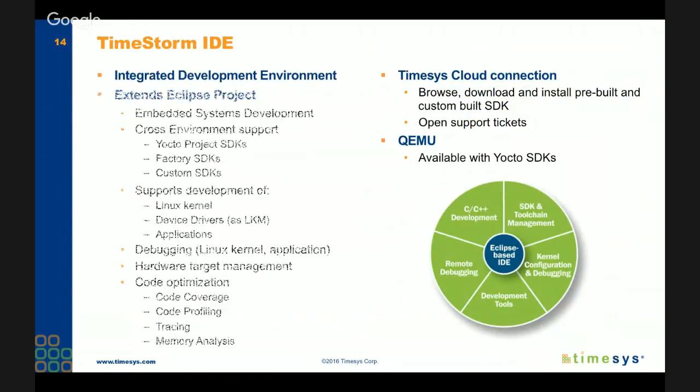Another tool that I wanted to briefly introduce to you is an IDE. An IDE that Timesys offers is called Timestorm, and it's an Eclipse-based application that automatically recognizes software development kits that are pre-installed on your host. So as you are going to use the Yocto Project to design and build a board support package and software development kit, the Timestorm IDE will automatically pick that up and will make that SDK available for application development and system level development.